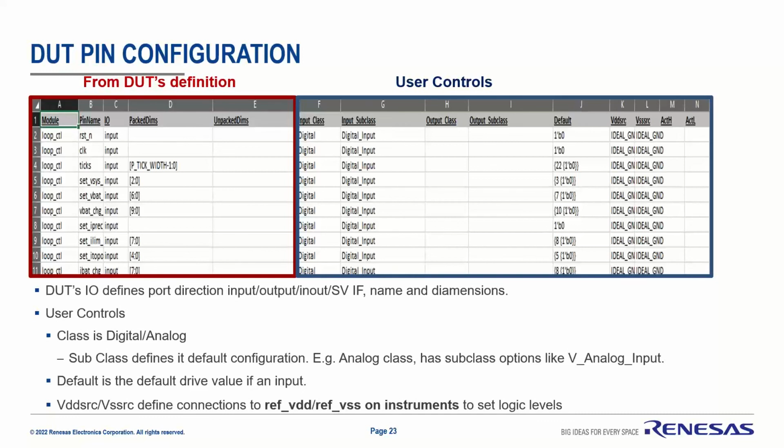So we use user-defined net types internally, and then we switch to analog where needed. But the whole point of UVM-AMS is you could extend that, your driver could use wreal, or whatever you think is best. It depends on the accuracy that you want versus speed.